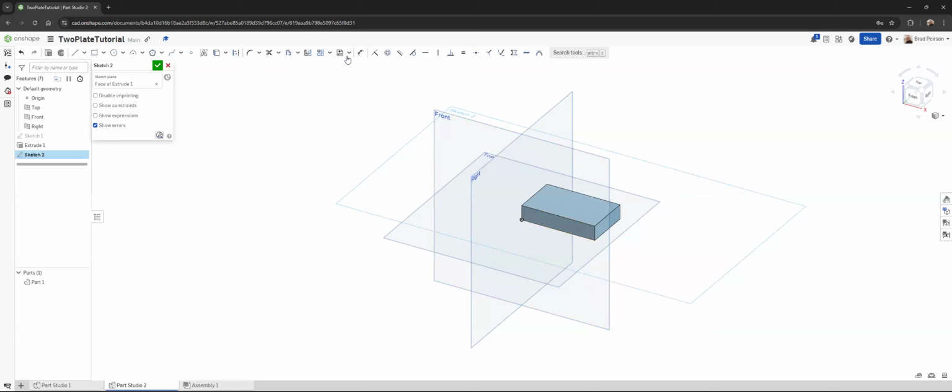So we're on that top plane hole. Where did you go? Oh, I need to put the points in first. So point, point, point, point. Now I noticed a dotted line as I was doing that and I didn't talk through it, but it automatically applied those constraints. No control, just click. And it automatically applied those constraints when I clicked with the dotted line visible. So that's a thing to maybe watch out for.